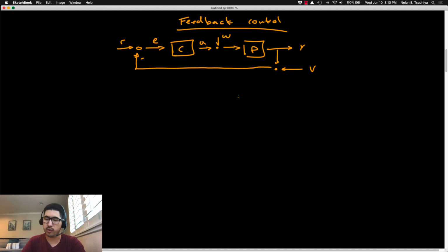To do that, we have to refer back to our block diagram algebra. Block diagram algebra will allow us to simplify this block diagram to a point where it's apparent what the input-output relationship is for a given set of input and output variables. When we write closed loop transfer function, that's the overall transfer function that governs this input-output relationship. Here we're talking about the transfer function from the primary reference input to the primary measured output. This is the so-called main closed loop transfer function.